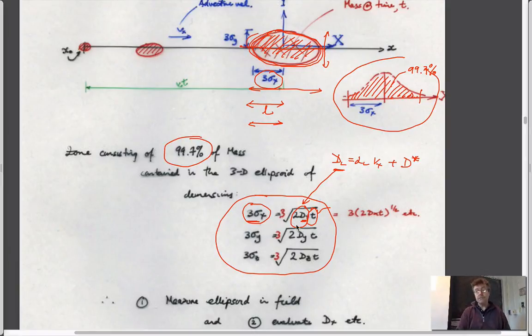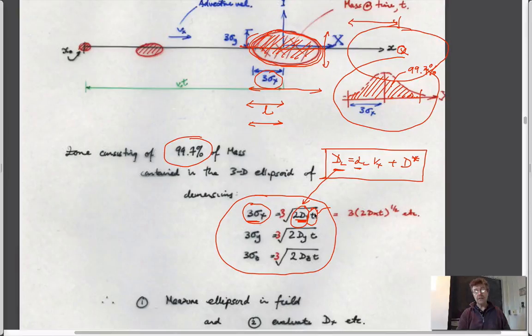Why do we want to do that, right? If you wanted to do that, you could get this. So what this would allow you to do is, if now you know what this dispersion coefficient is, and you think that nothing is changing in here, this parameter isn't changing, the velocity at which it's being advected isn't changing, and the diffusion coefficient isn't changing, then it would tell you that in some extra time, the center of mass would be at this location, and it would be bigger. And it would be bigger by some other amount, because now at some new time, you could calculate what the new size would be, and you could also calculate just from velocity times time, the length traveled, exactly where it would be.